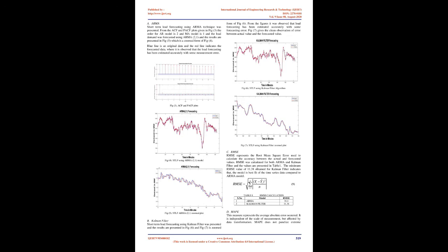The basic Kalman filter algorithm includes two stages of equations at every instant of time. They are time update equations and measurement update equations. In general, KF uses the current prediction error and current system demand data provided by the data acquisition system to estimate the next state vector. The time update equations are named predictor equations, while measurement update equations are called corrector equations.